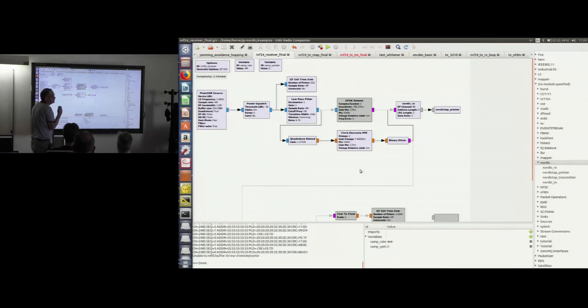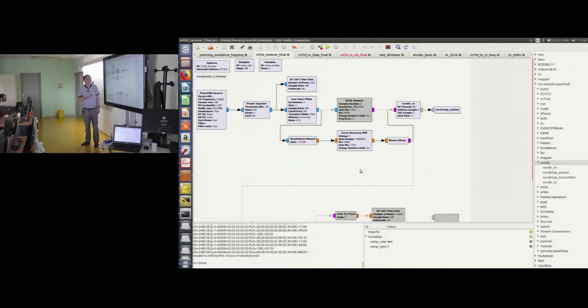And of course, something really important in digital communication is to have the right rate. So you've got a clock recovery system. It uses the algorithm from Muller and Muller. It's very well known. It's a publication that you can find easily on the internet, and it's quite interesting. It's not so complicated to understand. After that, you've got a binary slicer, just to transform what gets out here into 0s and 1s.